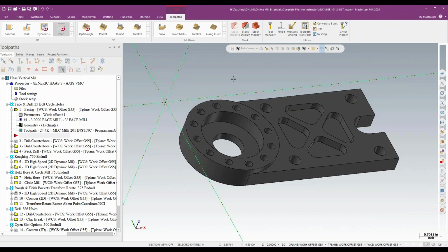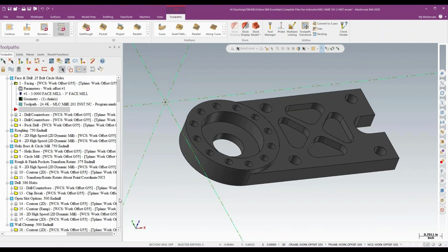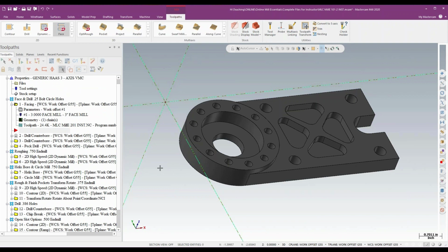So one of the things I really, really strongly encourage people to do is start building up a good database of proven toolpaths that you can reuse over and over, okay? So what I'm gonna do is show you just a real simple method for exporting toolpaths, organizing them, and then re-importing them in on future parts, okay? So I'm just gonna go ahead and pick a couple of toolpaths here that I wanna export, ones that I thought worked really well or they ran on the machine and they were pretty decent.